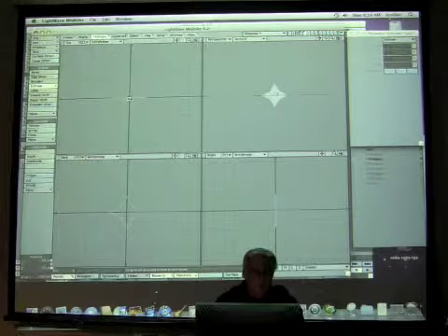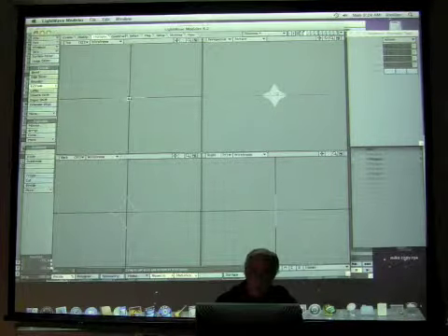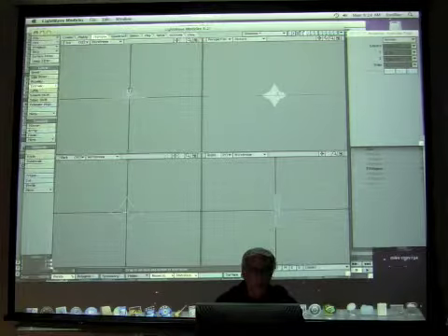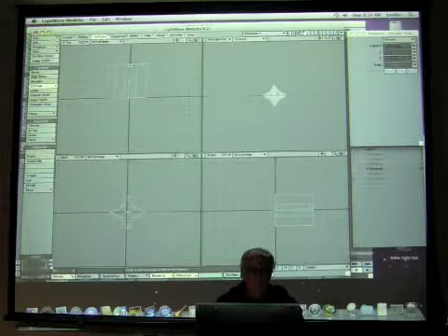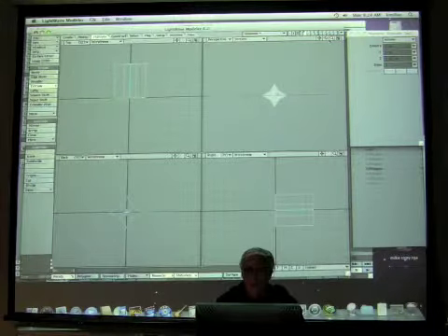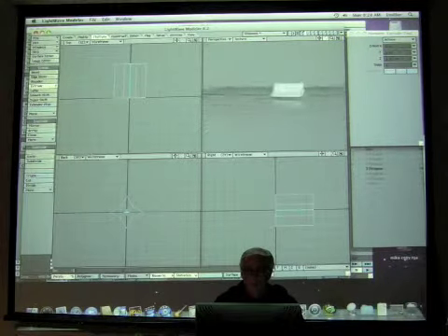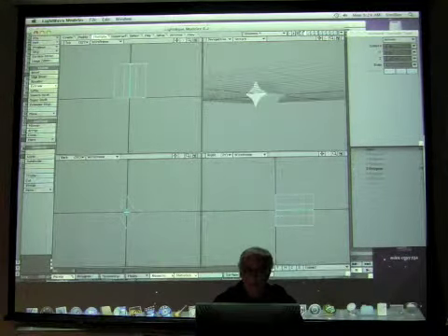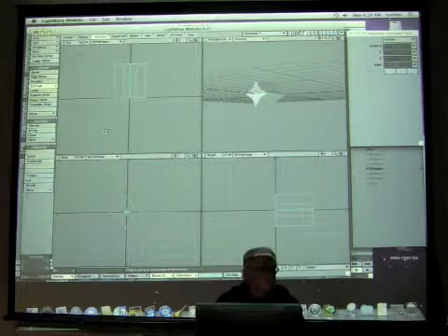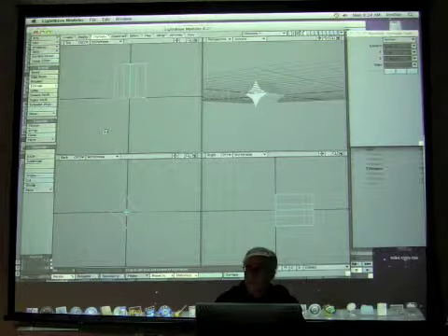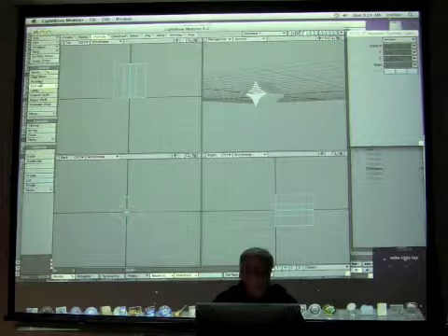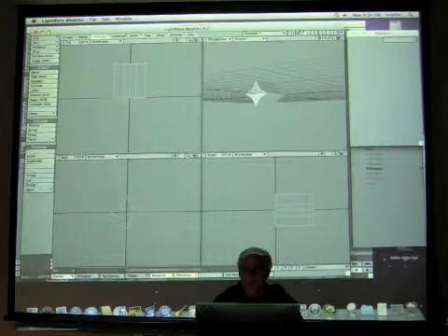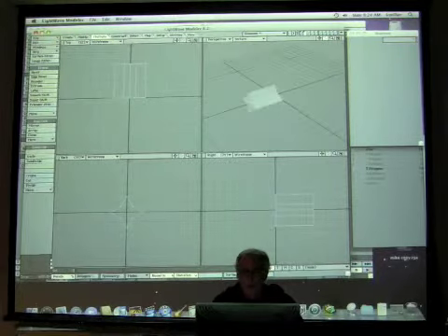So you work from the angle that's perpendicular to it, and you click and you drag. It doesn't have to be perpendicular. It can be at an angle, or it can be straight like so. Now when we look at it, this is the Play-Doh effect I was talking about. Now, if I select OK, I'm done with the extrude, and I look at this, it's correct.